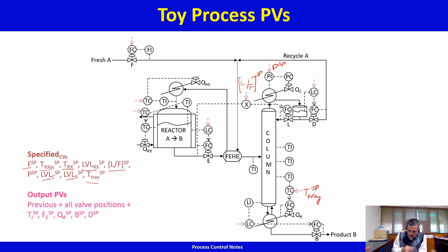Everything previously plus all valve positions which are adjusted by controllers, plus any set points that are being adjusted by master controller. So for example, reactor temperature controller adjusts the jacket temperature set point.